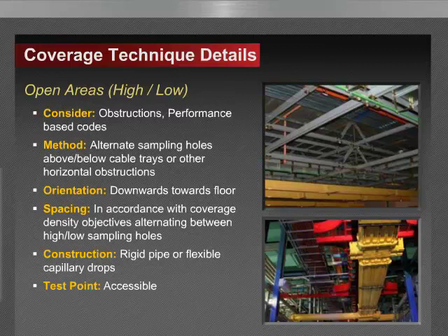Construction can be as simple as a rigid stanchion from the main pipe trunk, or to facilitate relocation of remote sampling points, consider the use of flexible fire-rated tubing and use additional lengths, generally in excess of 2 feet, coiled and secured for future relocation.